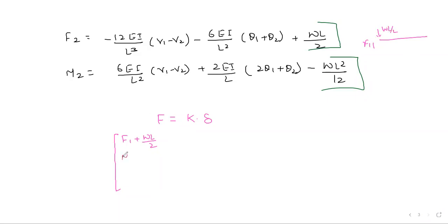For the moment we have M1 plus the fixed end moment. The fixed end moment was WL square upon 12, minus, right? It is in the same direction, so we will add it up. I am writing plus here; once we take the values we can write plus or minus as given in the question, but here I am taking plus, meaning the magnitude only. So M1 plus the fixed end moment. Because this is a UDL, the fixed end moment is WL square by 12.